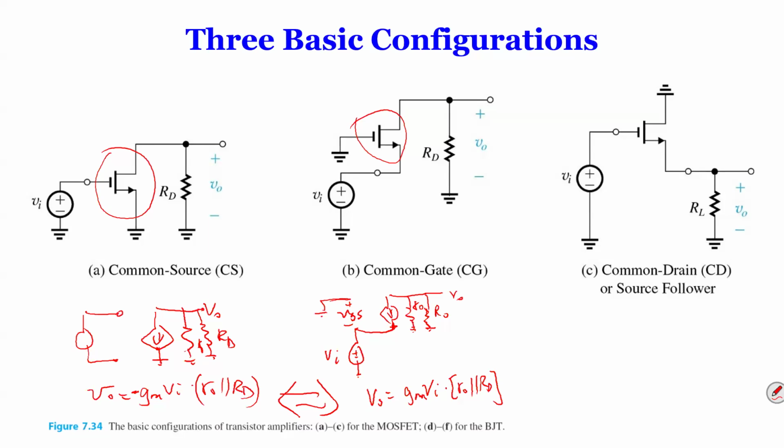So we don't have to worry about, when we're measuring the VGS, it's from the top to ground, right? What about the voltage drop across the current source there? Do we have to add that in to make VGS our output? No, this is the ground. So this is your voltage. You're measuring between these two points. So the total current goes here. This is VGS times GM. So the total current flowing through these two, so you got your voltage output.